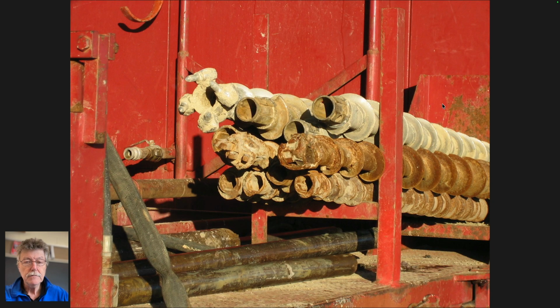Augers on the back of here. Same kind of, yeah, these are hollow stem augers. So this is a hollow stem auger. You have the pipe go down the middle. Obviously, you can't join these together by putting a clip across them, because then the hollow stem can't get across it. This is a cutting shoe on the bottom most hollow stem auger.